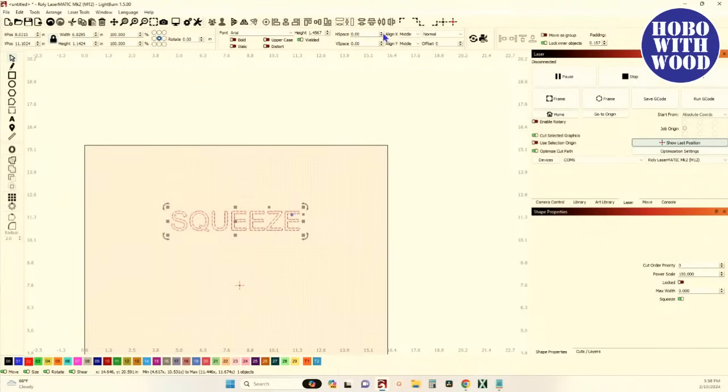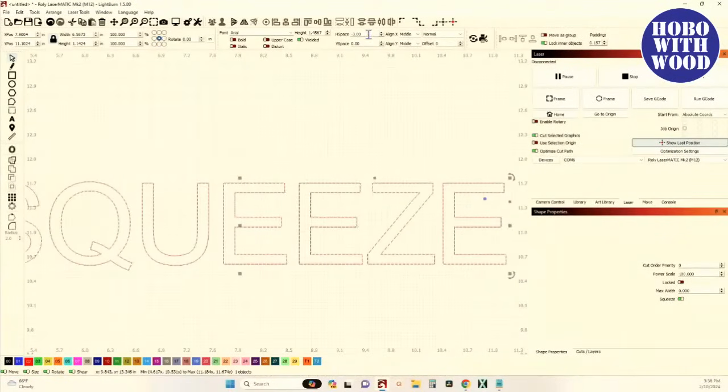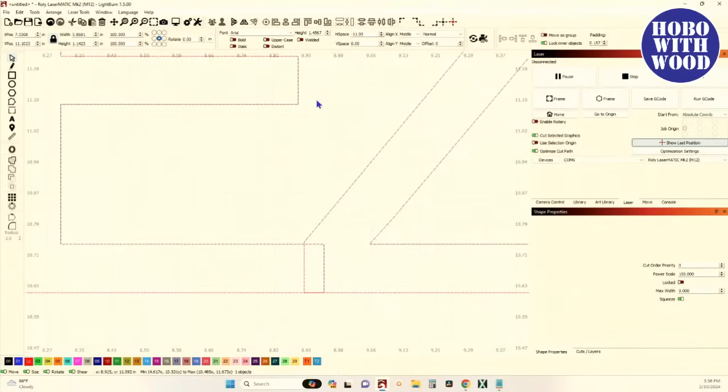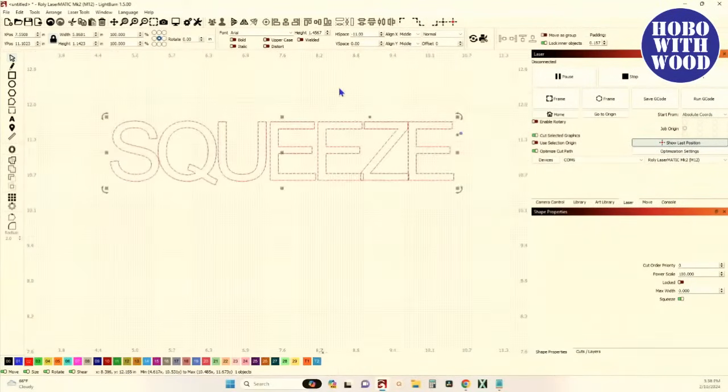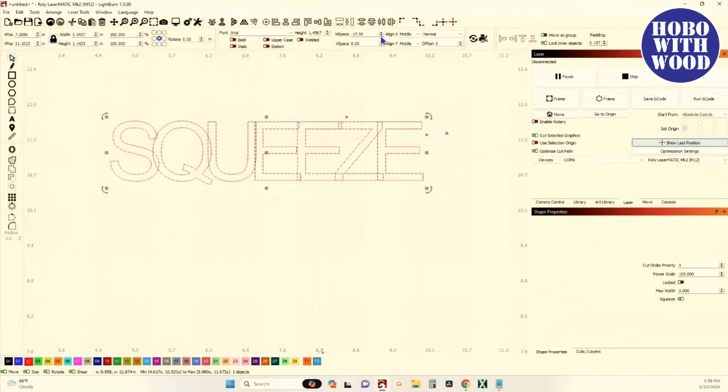And if I come up here and change my horizontal spacing, I can bring those either further apart or closer together. If I zoom in tight where you can see this real good, and I bring this all the way down and just keep bringing it, they will eventually start to overlap. I've got weld turned on, so I'm going to turn it off now. You can see the letters begin to overlap each other. And if you bring it together far enough, you can get all the letters to overlap. And this is how I generate that file, Amazing Grace and all those. Turn on weld. So now that's a nice welded piece. Yep. But the squeeze feature, put that back to 0.